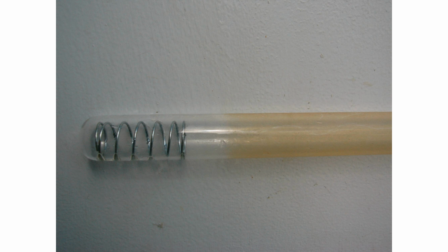You can sometimes get a little bit of UVA through the window, but UVC doesn't pass through glass, but it does pass through quartz. So this is a special, very pure silicon dioxide that the UV is able to pass through, but not if, in this case you can see it's orange, there was some accumulation of iron deposits on this lamp sleeve as it was treating the water.